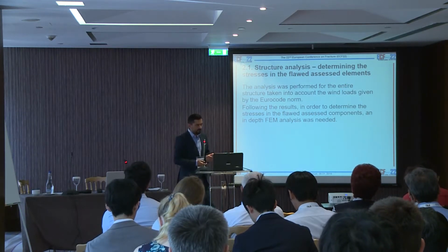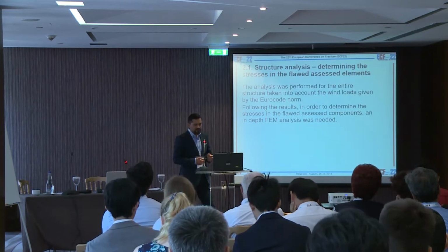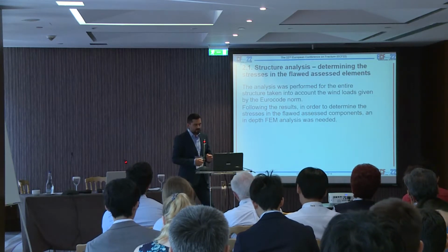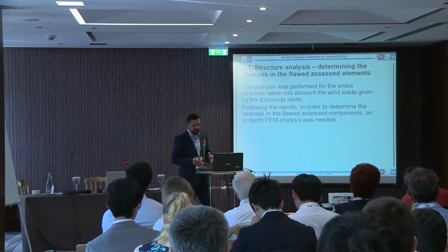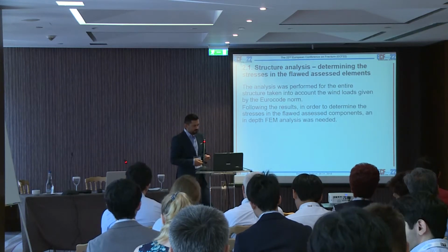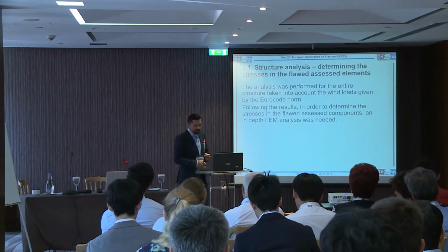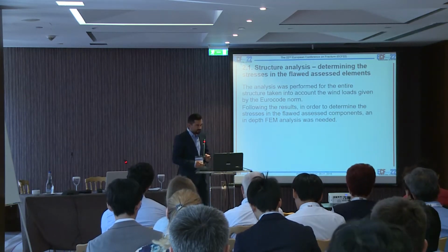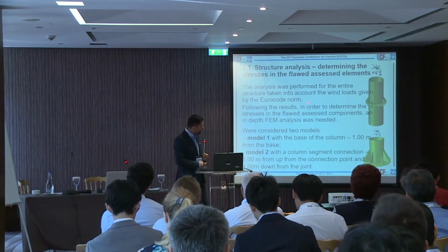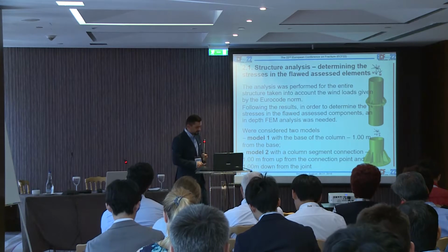And after the design phase, we wanted to have a more in-depth analysis. A finite element method was needed for assessing the stresses near the joints, especially the joint at the foundation and the segment joint, the first segment joint. The wind loads from the Eurocode were applied, with a recurrence interval of 50 years. We'll see immediately. So 2 models were used: one, as I said before, for the connection at the base, and one for the first segment to the second one.